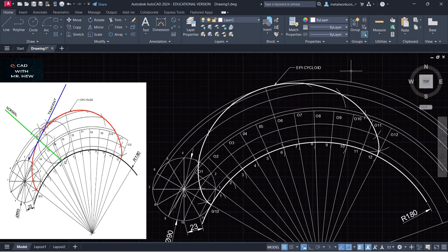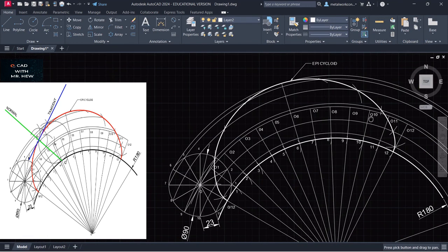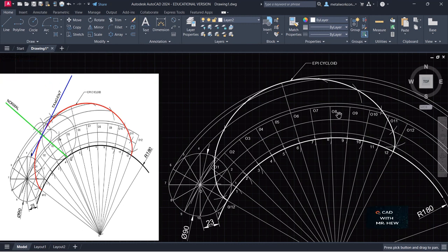All right. Good. Now, what we can also do, we can also construct the normal and tangent to the point. I'm going to draw a random line down. All right, enter. So point P, I'm going to label P there. So I'm going to come single line text. I'm going to click right here. The height must be 6. So this is P.